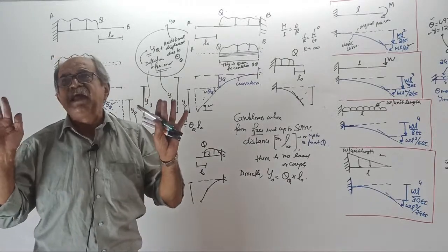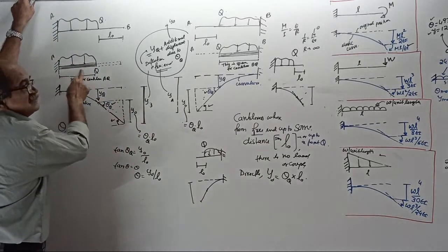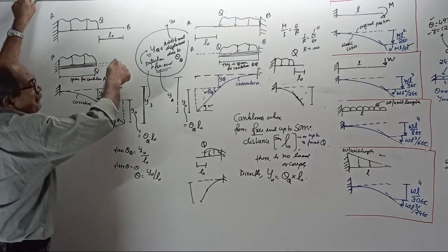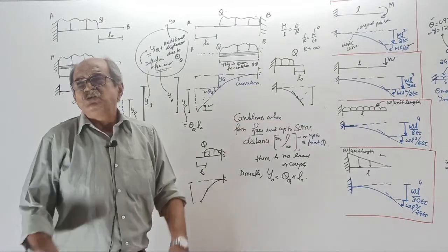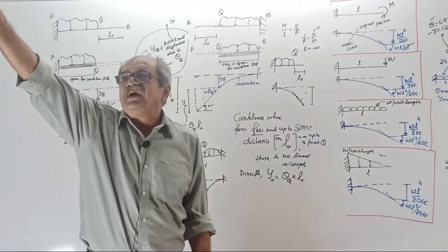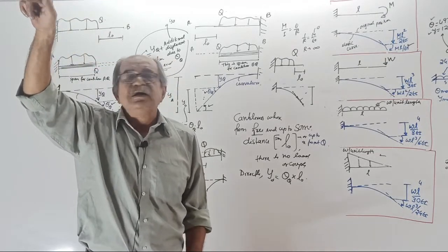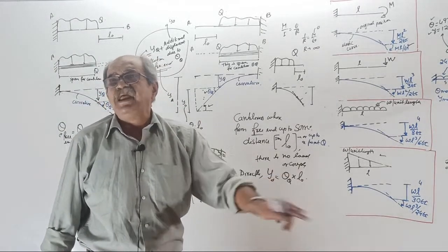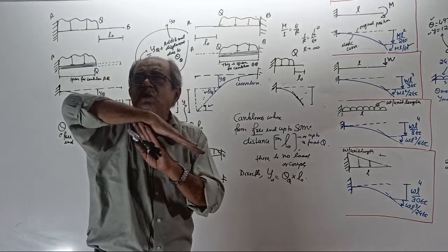That you have to find like a cantilever, and the span is only this much. Now you get slope and deflection here. Then if you want the slope and deflection at the free end, you don't have to find the slope. Whatever slope came at the end point before the straight line starts, that itself is the slope at the free end, because for a straight inclined line there is only one slope.